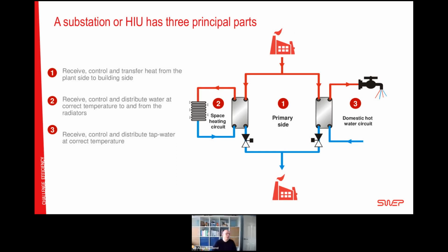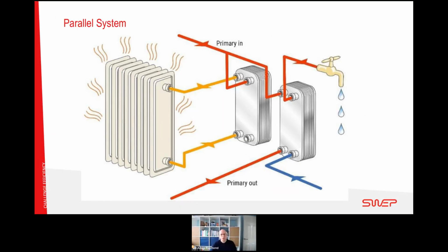The working principles are very much the same for both of them. We've got the district energy coming in from the top, the primary side, going into each heat exchanger, a series of metering and control valves, of course, and then delivering indirect and hydraulically separate space heating and tap water as well on demand. When we look at how a substation is constructed to deliver the same result, but deliver it centrally through all the different dwellings, it's very much the same type of approach.